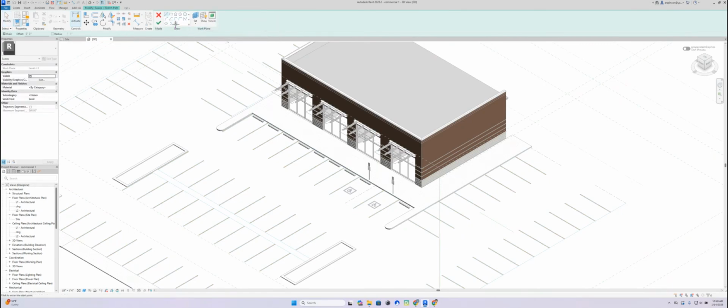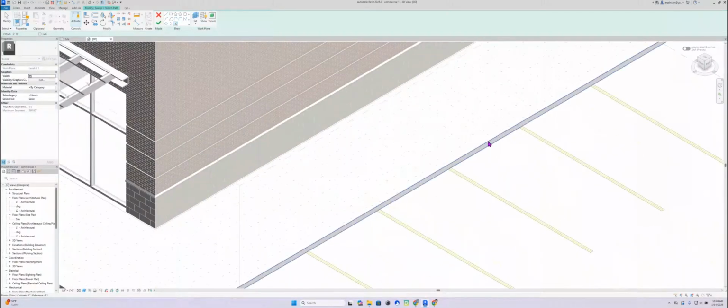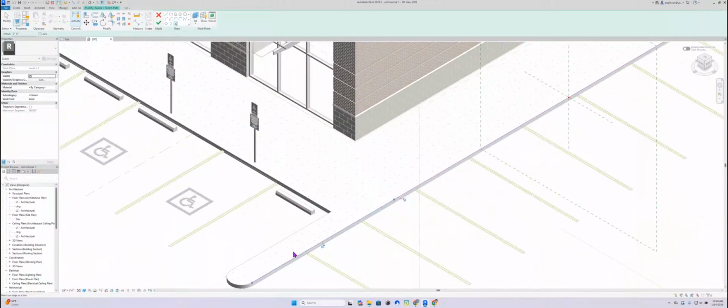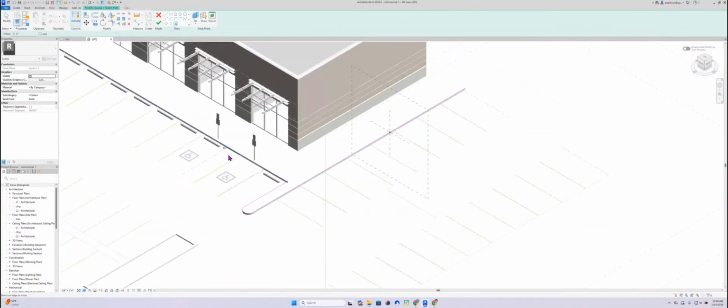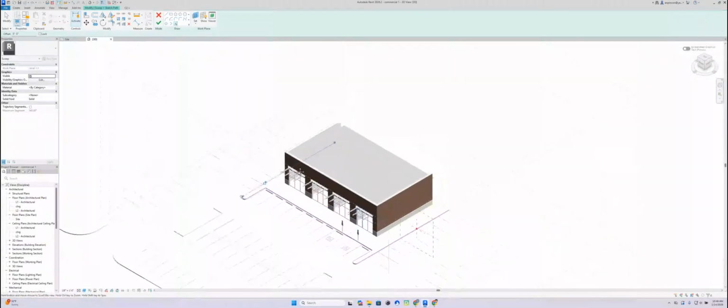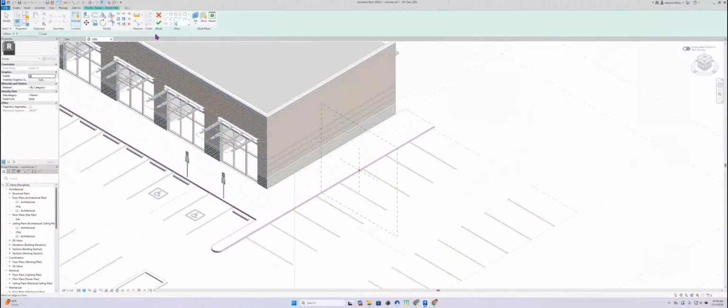I'm going to use the Pick Line tool, zoom in, and pick the upper line, and go on every line segment of my project. Basically, I'm going to try to stop it here. Okay, that's it. I am done with the path, so I'm going to finish it. Then I need to edit my profile, which is going to be right here with this crosshair.